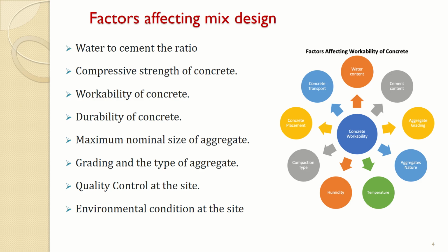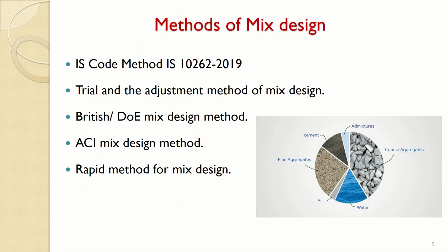In that, you know that coarse aggregate plays an important role in getting strength in the concrete, because coarse aggregate normally consumes around 70 to 80% volume of total concrete. Hence, to get durable and good concrete, your aggregate quality must be very good. Otherwise, if you are using more cement or other particles, that will also not be of any use. Hence, by knowing the local conditions and the structure requirements, accordingly you should design the concrete.